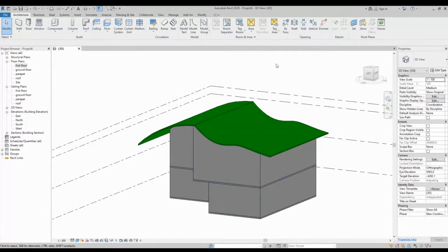So when we were creating openings in wall, we said that we can select wall from here and create an opening. Otherwise, you can edit the profile of the wall, or you can add a door, and the type of the door is an opening.